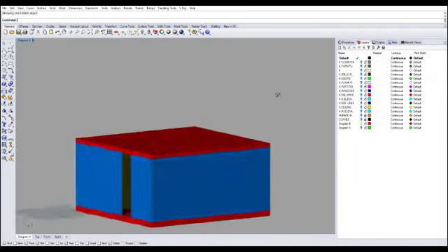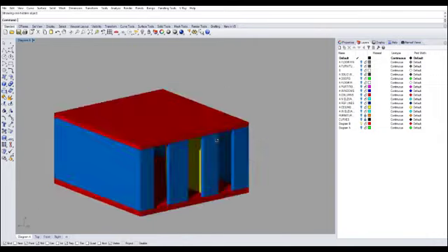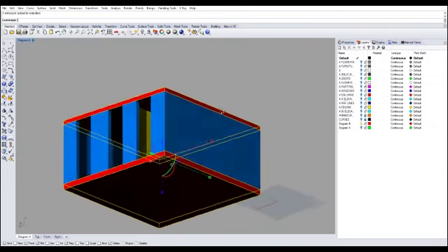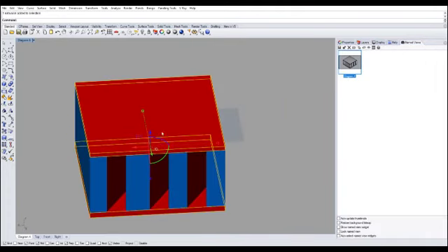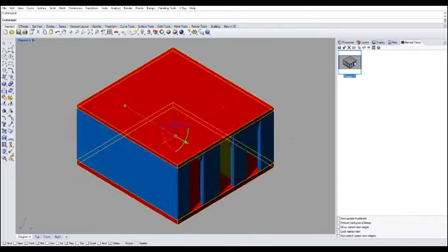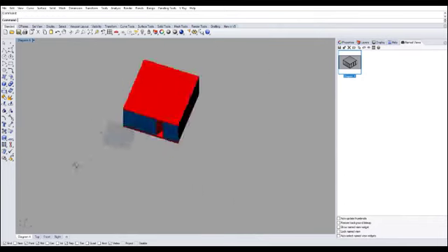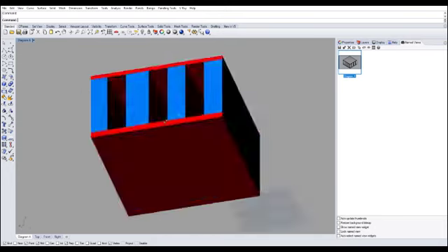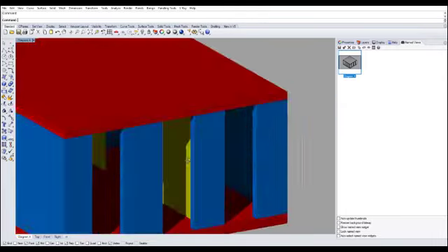So to render this series of component diagram renders, instead of rendering the whole thing, we're going to render them one component at a time. By the way, we're going to keep the ceiling and roof as one component. And as before, we're also going to make sure that all of our renders are only in the diagram A view. Same thing as before. If you're on any other view, make sure you double click diagram A view.